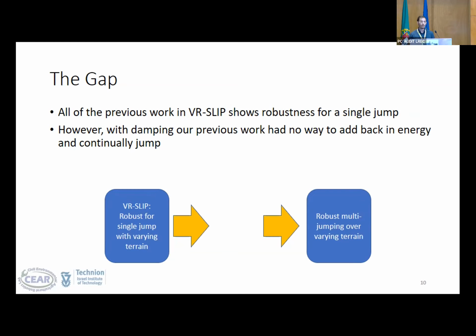So in order to explore this further, we gave each leg the goal of 50 hops over 30 randomly generated terrains for each rise. And we found overall that the higher jumping leg had a higher degree of survivability. We suspect this is simply because a higher jumping leg has a higher clearance, so it's able to just clear any terrain that would be problematic for other legs.